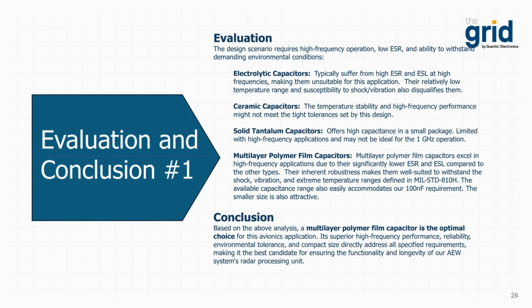Now, solid tantalum capacitors offer high capacitance in a small package. However, they do have limitations with high frequency applications and might not be ideal for this 1 gigahertz application. Also, their failure mechanisms are potentially catastrophic, something we need to minimize.